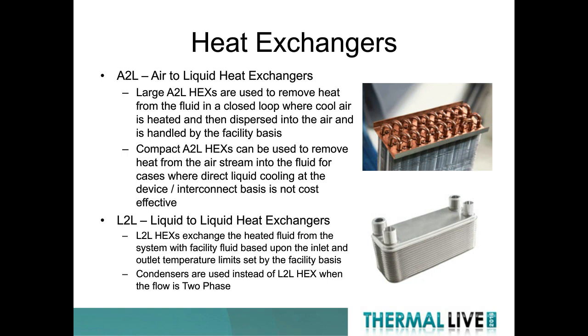So if we have just a few cold plates on the large heat generating devices, but there's a lot of smaller components that are dissipating heat, we could use a heat exchanger in that airstream to capture the rest of that heat and then put that into the liquid. And there's times where that becomes cost effective.